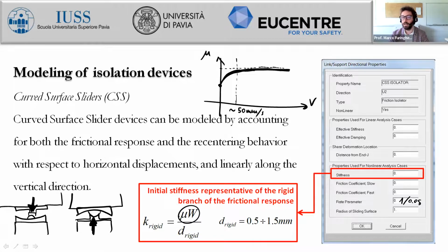We will consider a very regular 3-story structure. We will guess sections, and once we compute the overall mass of the structure, we will try to define the isolation layers. Then in the laboratory, on Wednesday, we will perform a nonlinear time history analysis with the software. And on Tuesday, we will proceed with the selection of the seismic events for the nonlinear time history analysis.